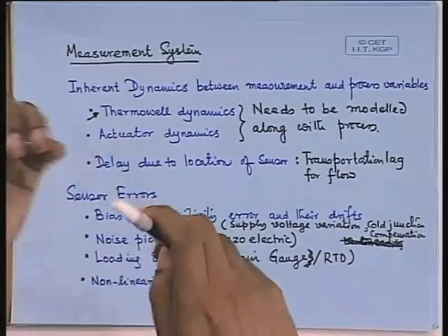If you are using the UK values which are there in your computer and think that actually that is going to the plant, it's not going to the plant, it's actually going through the actuator. So there could be significant actuator dynamics, and when you are estimating, what you are thinking as UK is not really UK.